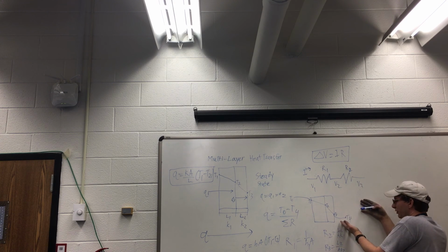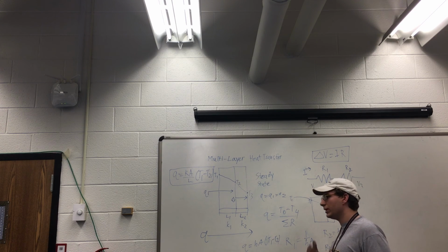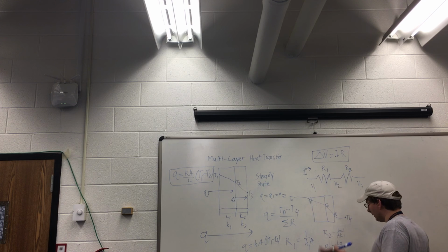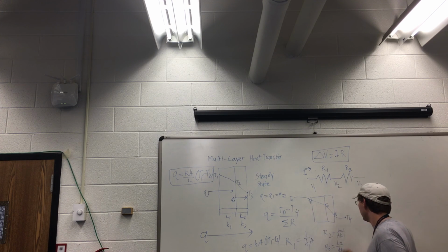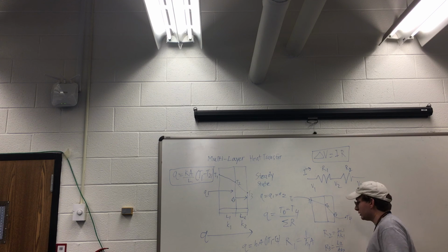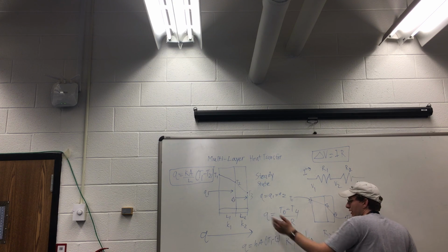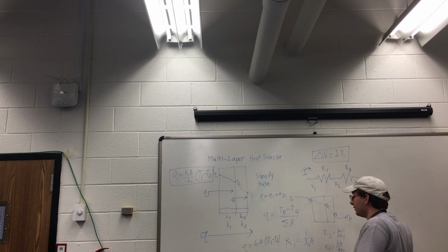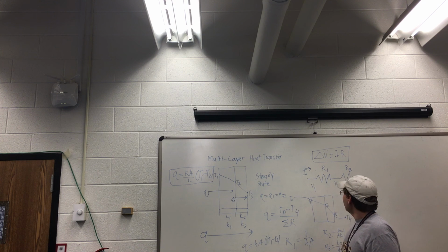And if we have just a breeze out here, the different wind speeds might change how the heat is transferred from T0 to T1 and from T3 to T4. So pretty much all that would be left to do is sum up all of these terms here. You have your temperature differences, so you can find the heat flow or anything else that you would need to find. And I believe that's a wrap.